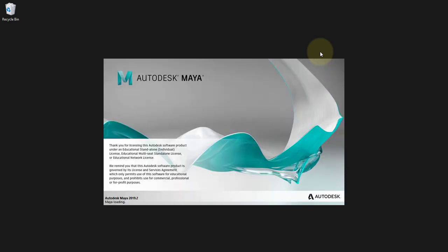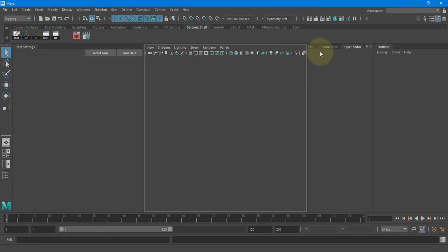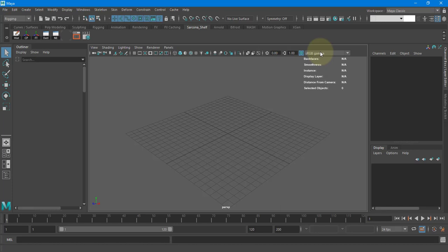So on makeatmacomb.com, I put up a new video. It's Polygon Tools, okay? So that way I don't have to go through this and talk about every single Polygon tool that I use. Go through that video, you can see, like, here's the tools that you should be using when you model stuff. So far we've used Bevel, Extrude, and Insert Edge Loop.